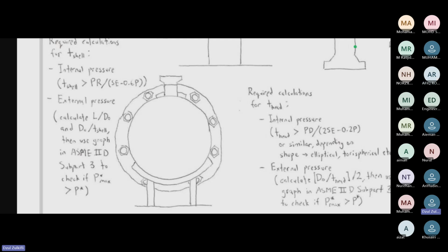What happens is that the vessel will have a vacuum inside of it, such that outside the vessel there is just normal atmospheric pressure, but because of the vacuum inside, the vessel must have sufficient thickness so that it doesn't crush like a tin can. If you can imagine it. So when we talk about external pressure, it doesn't mean there is some very strong pressure or gravity outside, but rather there's a vacuum condition inside the vessel and you need to have sufficient thickness.